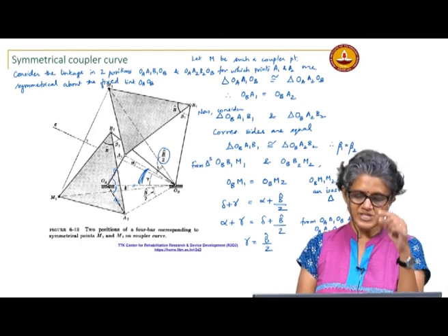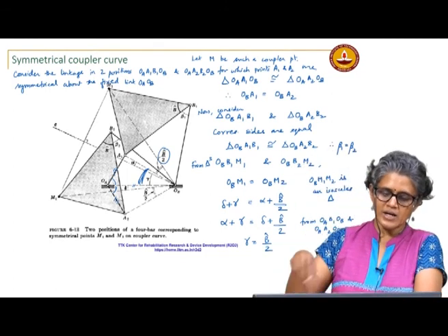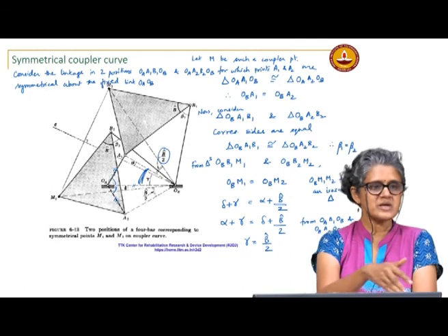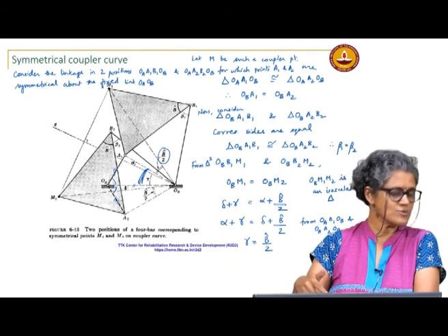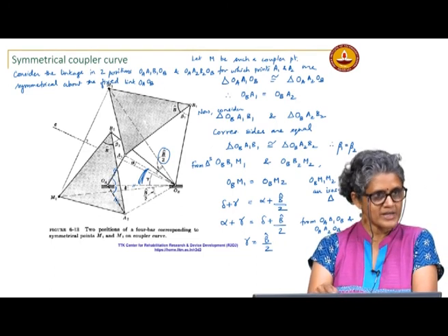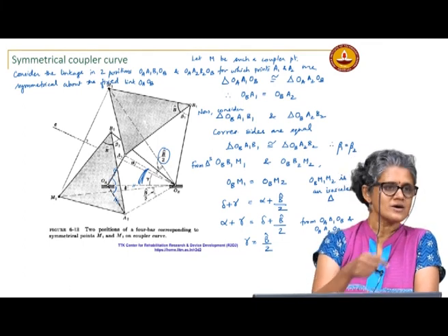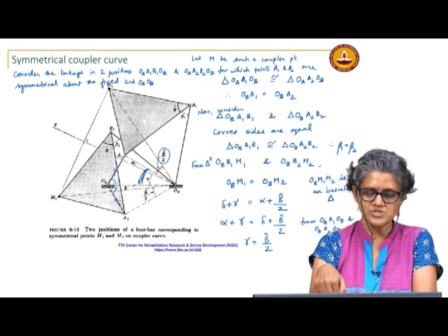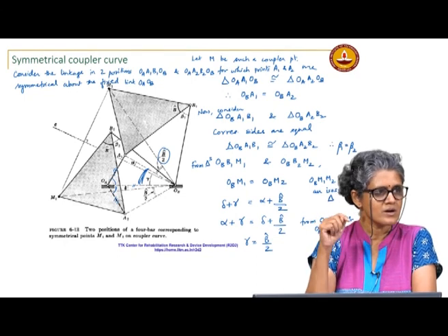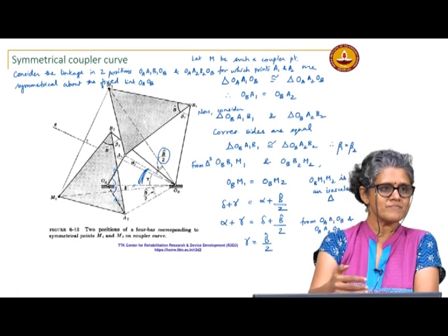Okay. So, to find a coupler point with a certain line of symmetry, say I want a line of symmetry at a certain angle to the base, I would take the follower length to be equal to the coupler base, draw a circle centered at B that passes through OB and A1, and then choose that angle as twice the angle.